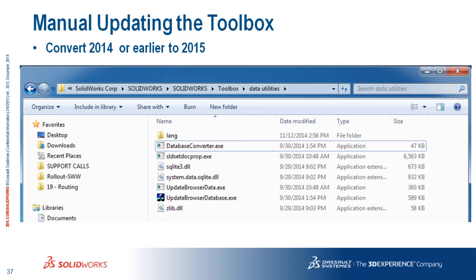Okay. If you followed all the tricks so far, you would have gone in and said, hey, I made SOLIDWORKS 2015 and I'm going to 2016. When my update fails to install, what toolbox am I going to upgrade? My 2015 one, right? I named it. We're all good. Know exactly which one it is. That folder naming can be done during the install process. You can go back and change it later on, but then you have to switch your options, repoint to it, okay? So try to do it during your install.